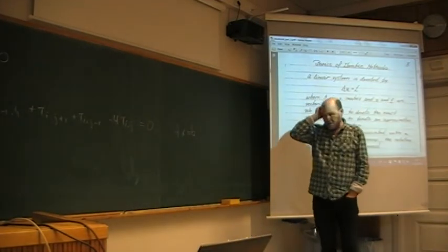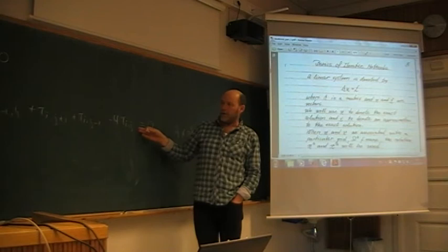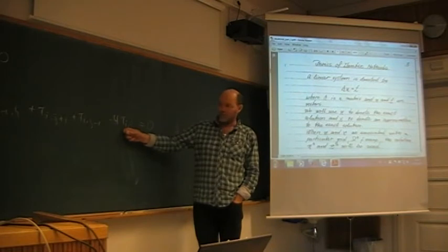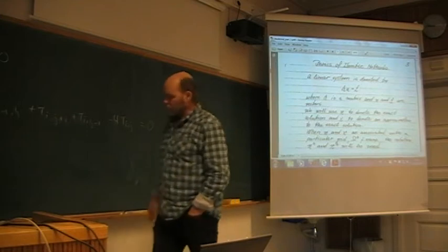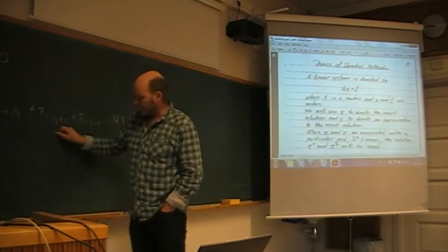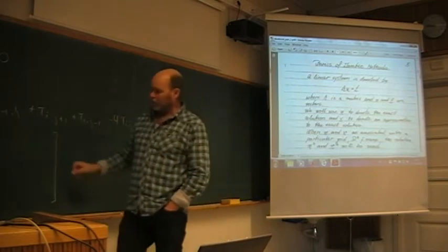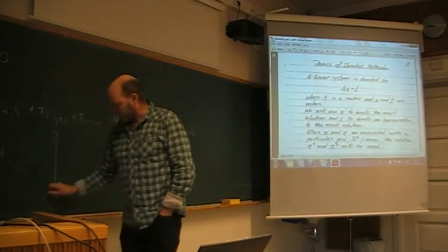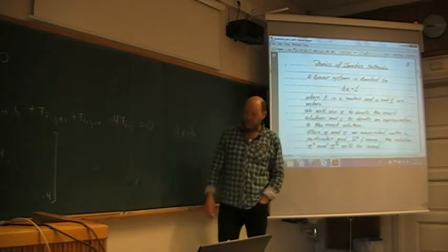So that was the discrete version, using a constant mesh, delta x equals delta y. And then it's a question of solving this algebraic equation system. So here you will now write this as a matrix system, and your coefficient matrix, how will it look? Well, the diagonal, that's the center point, will look like this. It will have minus 4 all the way down here. And then you have 4 neighbors.